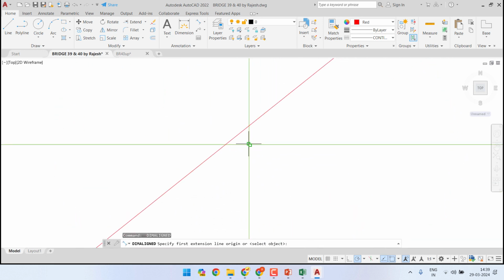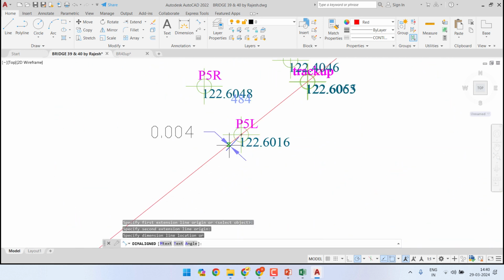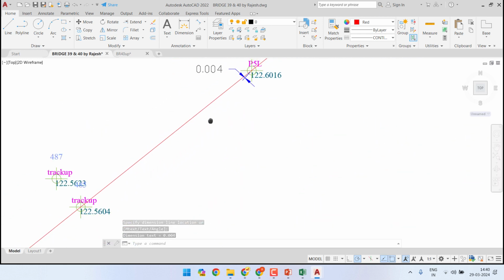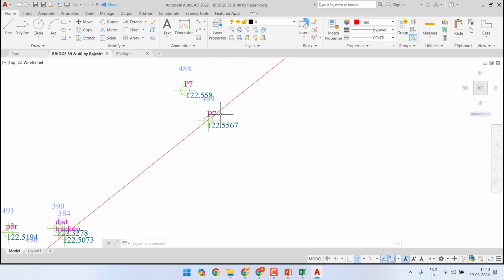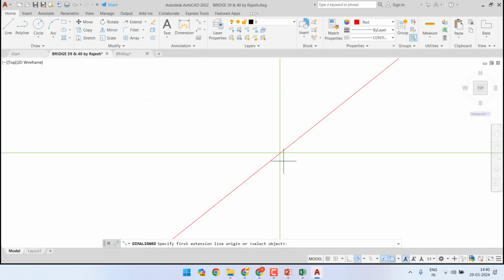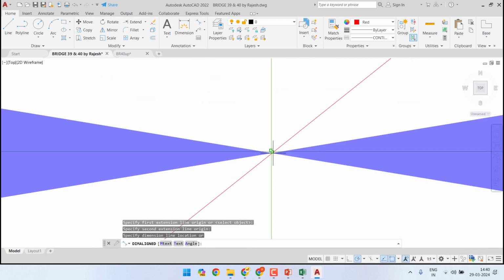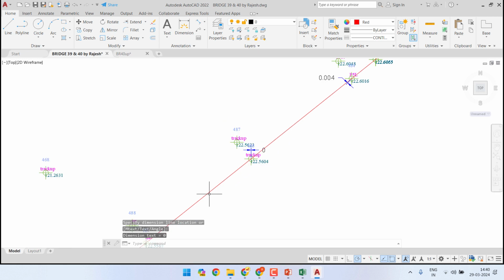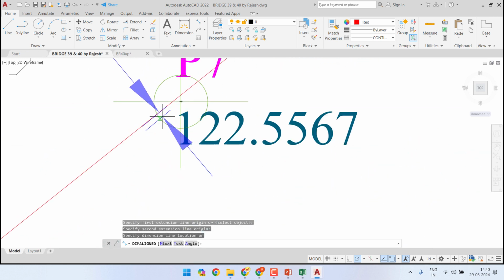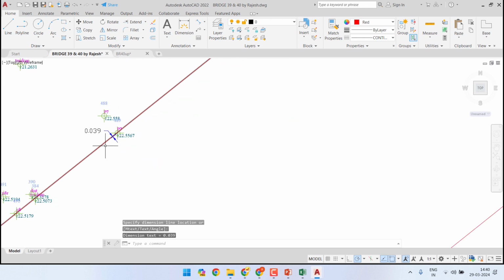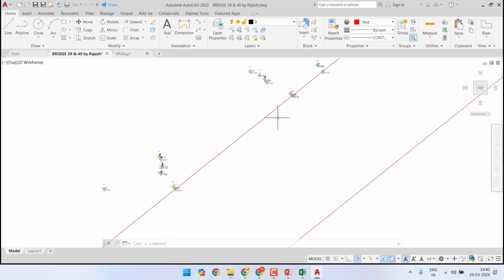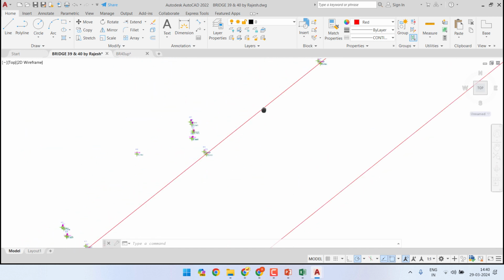Now the error has reversed actually. In this case, we need to slew the track 4 mm to the right side. This was +6 actually. It is almost 0 actually. Then +7, 39 mm to right. So likewise, we can find all these points, and up till